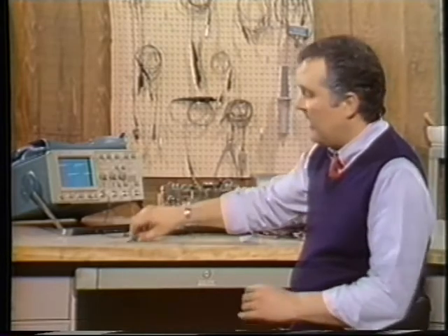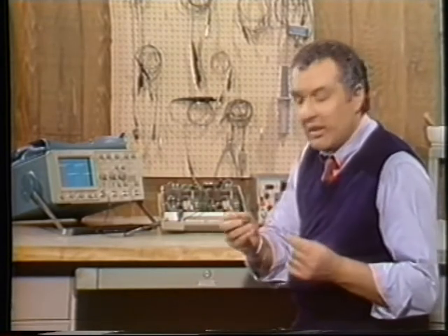Oh, I'll concede it may seem trivial. Circuit under test here, oscilloscope there. Question: how do we get the signal to the scope input? Well, the obvious answer is a microhook and a wire. Clever and resourceful, eh? Amazingly enough, it'll even work if the signal is DC or very low frequency and we don't pick up stray EMI. All we add is the resistance, which hopefully is known, of the wire to the circuit.